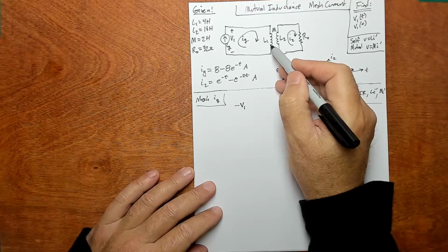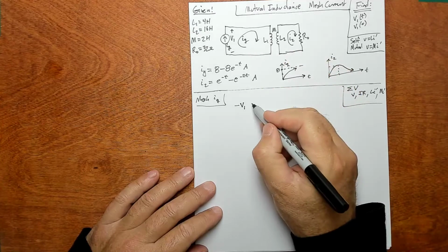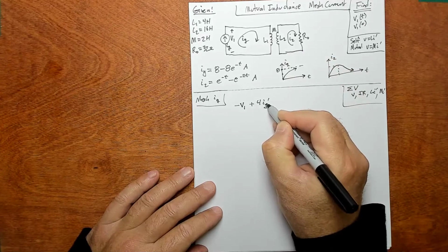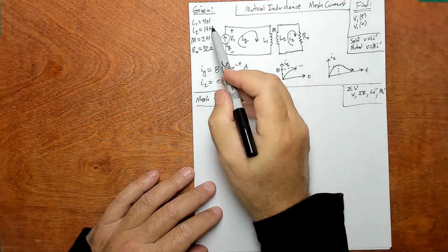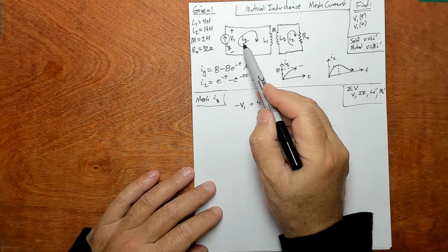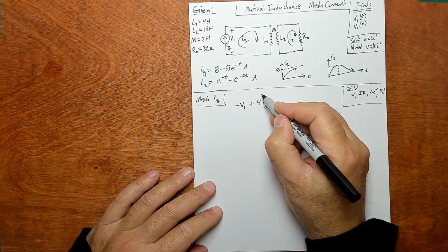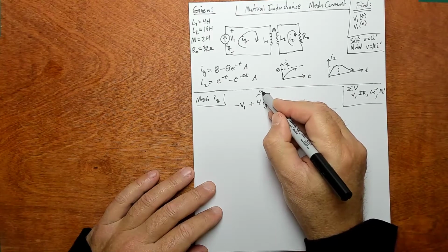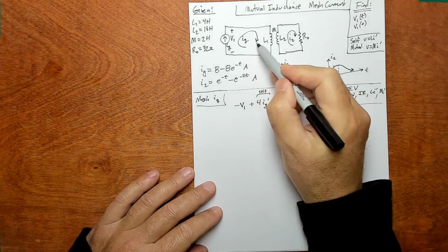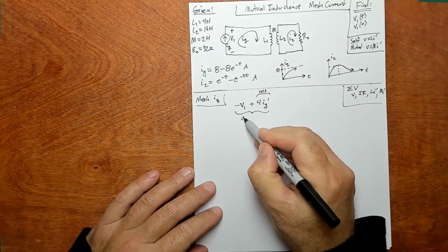So there's a voltage across this inductor here due to Ig, and that's just L Ig prime. This is the self inductance, the inductance of this inductor times the derivative of the current through it. So this is self, and you could label that right here as self. And that's the primary terms, the terms due to Ig.